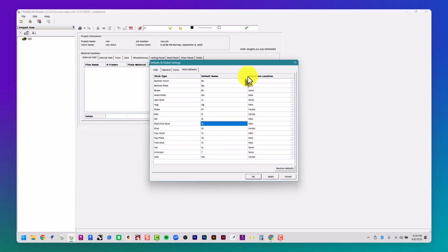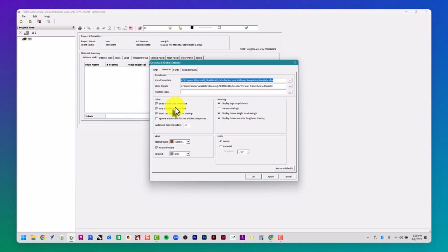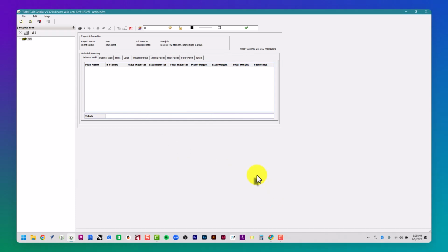And then General. So here under General, I can change my units, and it's important to change your units to metric when you're trying to affect your tools and your lengths of your actual machine. The machine itself was designed in metric units. So therefore we want to switch this to metric when we go to set up our machine. So I've already done so here, and then I'm going to hit OK. And then the next thing I'm going to do is go to Edit, Machine Setups.